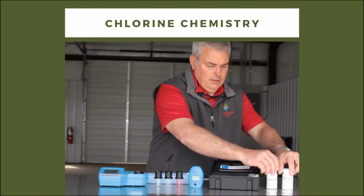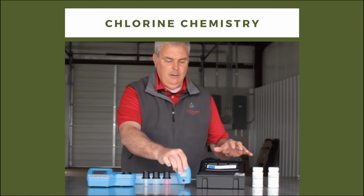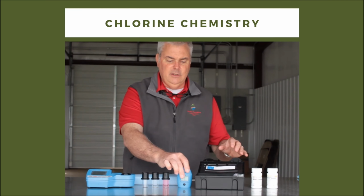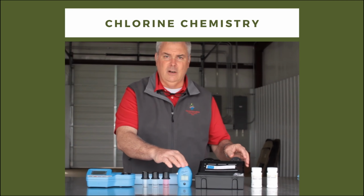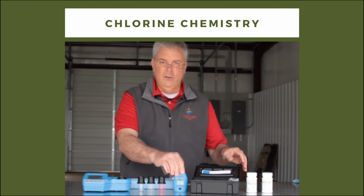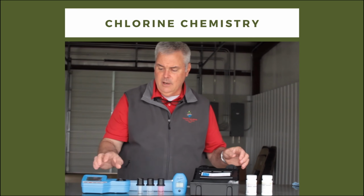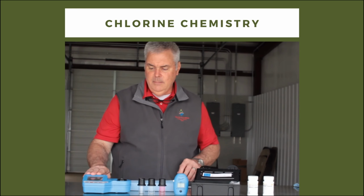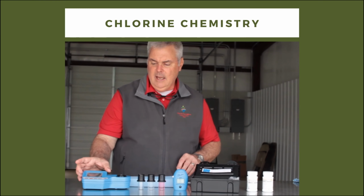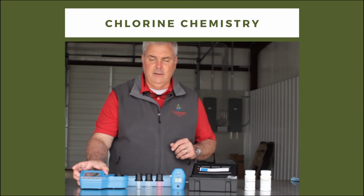In addition to the test strips, we have two different chlorine meters. These are relatively expensive. One of the disadvantages of this type of meter is that it can only measure up to 2.5 milligrams per liter, but it's relatively inexpensive, less than $100. This meter will go up to 5 milligrams per liter, and it is more expensive, but it's still less than $400.